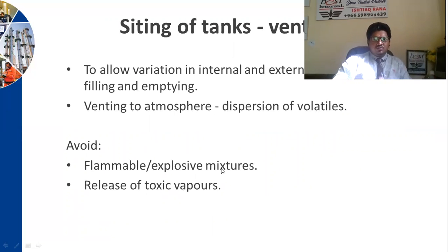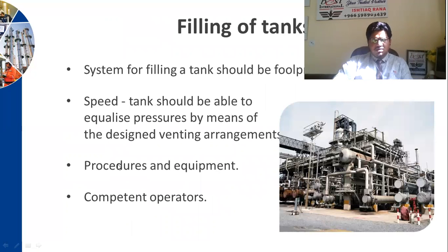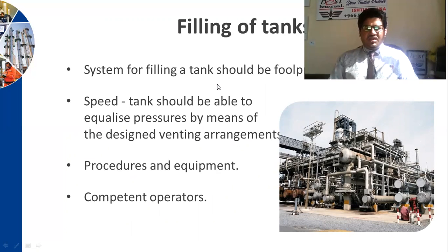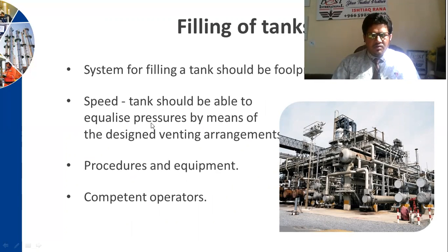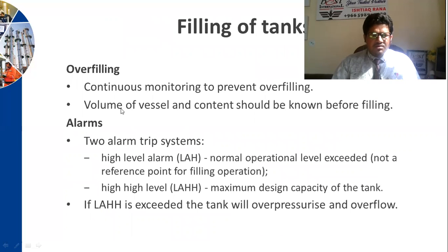Setting of tanks: ventilation to allow variation in internal and external pressures during filling and emptying, venting to atmosphere, dispersion of volatiles, avoiding flammable explosive mixtures and release of toxic vapors. Filling of tanks: the system for filling a tank should be foolproof. The tank should be able to equalize pressures by means of the design venting arrangements, procedures, and equipment, and competent operators. Overfilling: continuous monitoring to prevent overfilling. The volume of the vessel and its content should be known before filling.